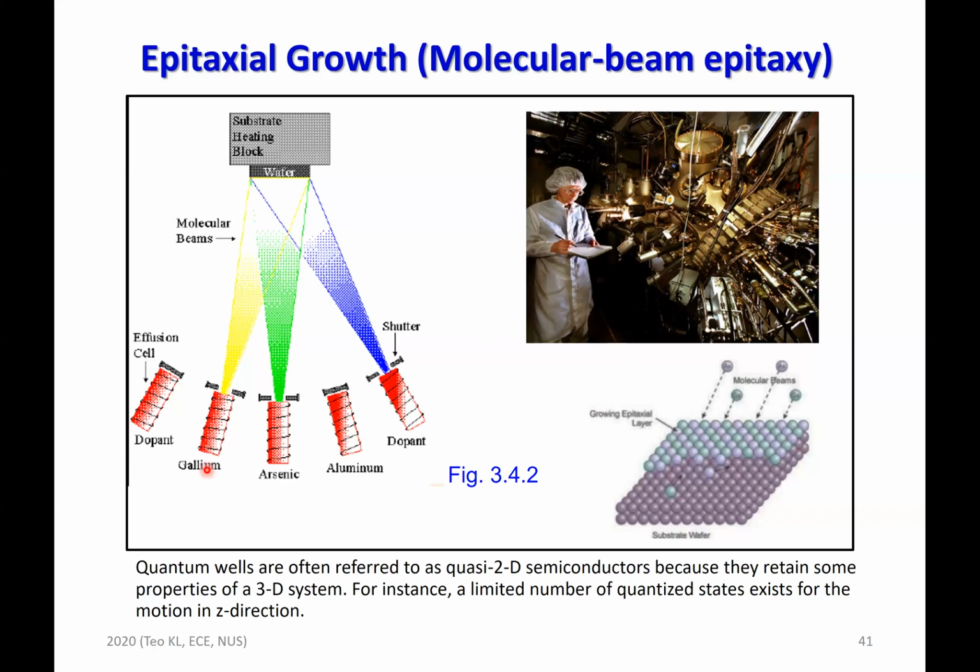So again, all these gallium and arsenic elements, or solid sources, in ultra pure form of 6N, 99.9999, are heated in a separate diffusion cell until they begin to slowly sublime. Sublimation, or we say the atoms sublime, is a transition of a substance directly from solid to the gas phase without passing through an intermediate liquid phase.